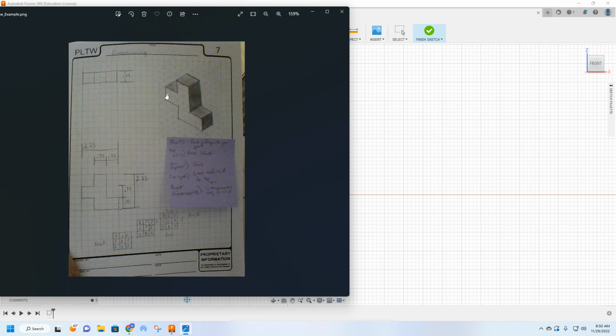So we're going to start at the origin, which is the 0, 0 part in Fusion. And we're going to draw an outline of our puzzle cube that is roughly the correct size, paying attention to all of our dimensions here. Now notice mine are 3/4 inch or 0.75 inches. Y'all's are 1/2 inch or 0.5 inches each. But that's okay. This is 1 up, 1 over, 1 up, 1 over, so on and so forth.